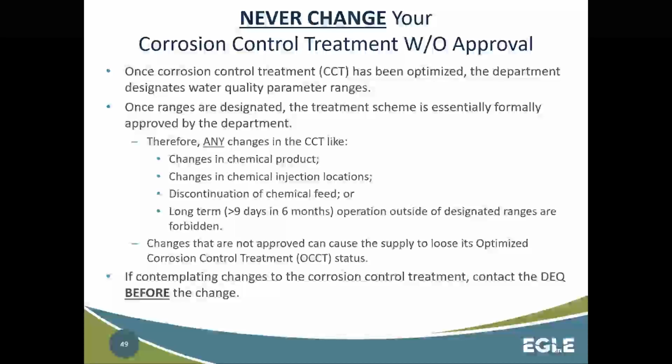Make sure that you're submitting your permits. Make sure you give ample time for review and things like that. We want to make sure that you are not affecting your water quality because it can and does have an effect on corrosion control. Okay. Those passivation layers can be easily stripped. We can have issues with them. So please make sure that you're not going through any form of treatment change or source water change, new wells, whatever that might be, interconnections. Make sure you're talking to EGLE first.